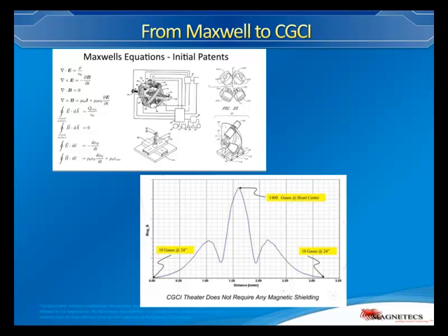The important part about our system, we call it dog on the leash. We basically have a very, very floppy catheter that we put a little bit of slack in, and Dr. Gang will talk about how he uses it in operation. Then we pull the magnetic field, pull the head of the catheter, and the rest of it just follows through. We give a little bit of slack coming out of a device called an advancing device that we will show you.